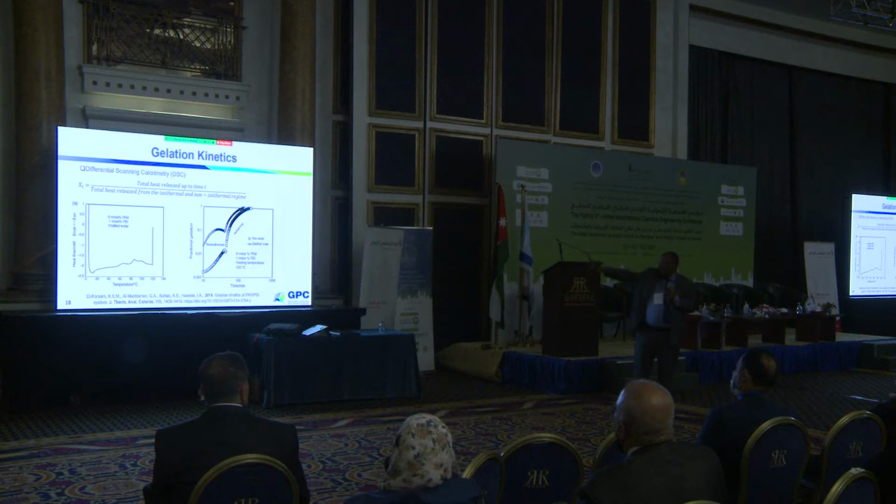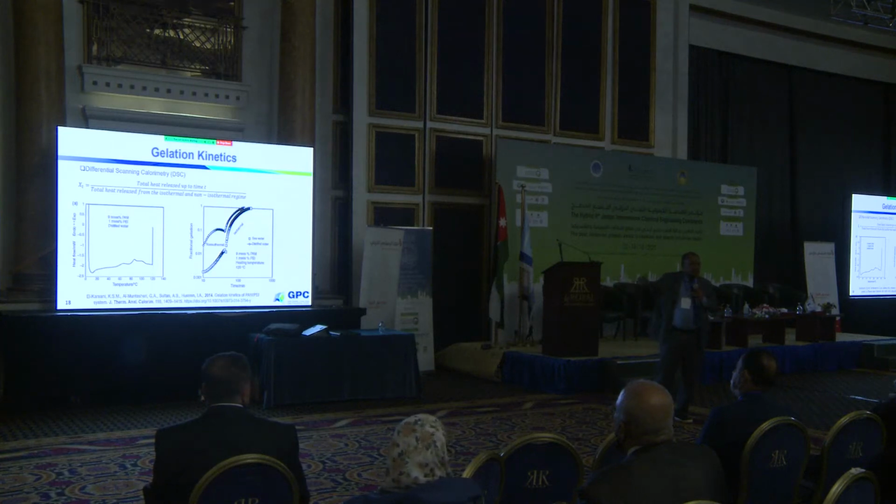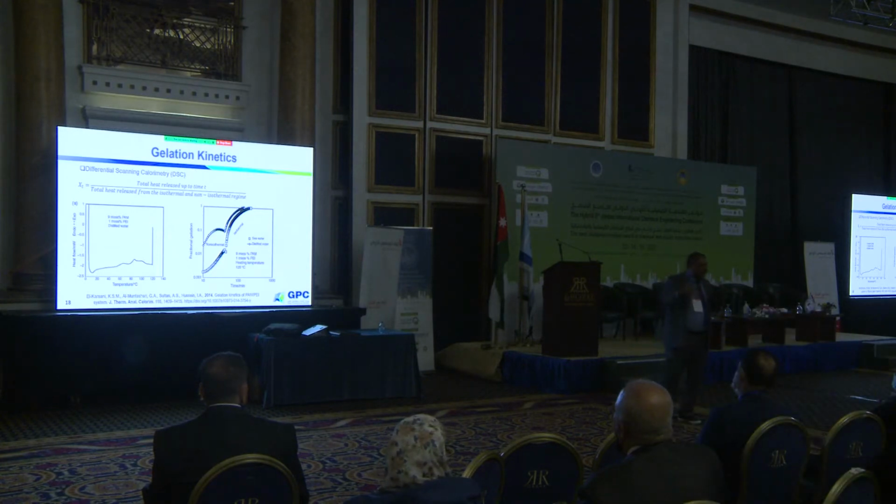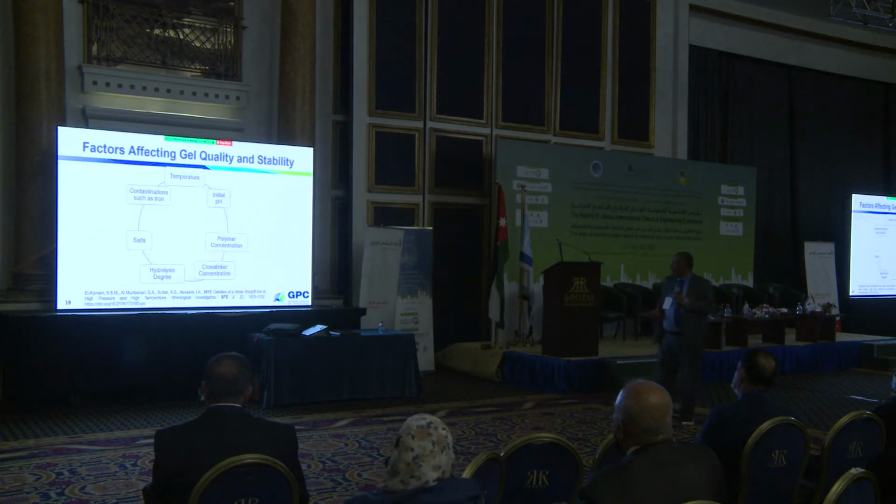Here I am going to talk about it rheologically and through thermal analysis. We can study what we call rheokinetics, or we can study the kinetics through thermal analysis, understand the mechanism, and play with the formulation, delaying the gelation sometimes using different chemicals, so we play with the chemistry to avoid any gelation during injection.